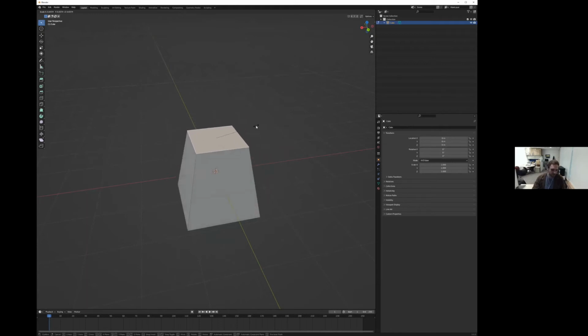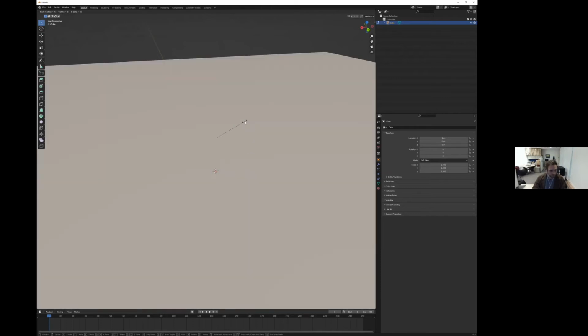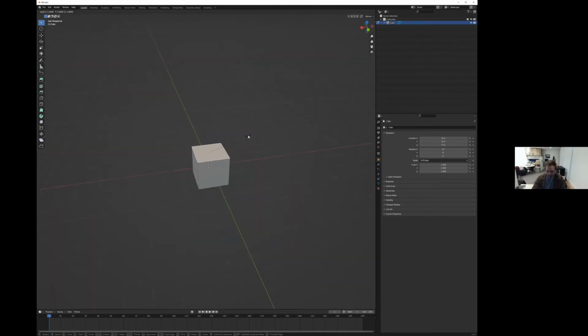If you wanted to be more fine-tuned or surgical, or looking at kind of a CAD model where values are important, you press S and then 1 or 2. So you scale it 2 times, or you can scale it 0.5, half of that. So there is that option.